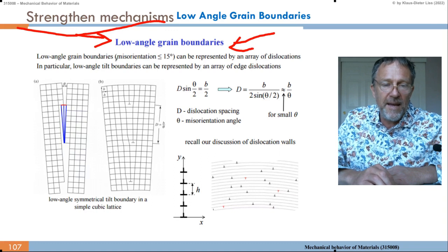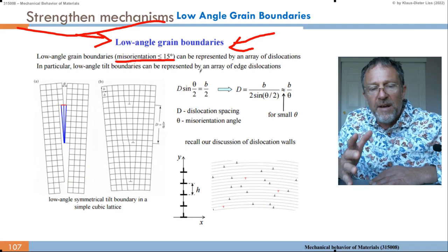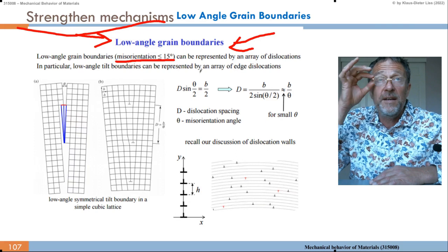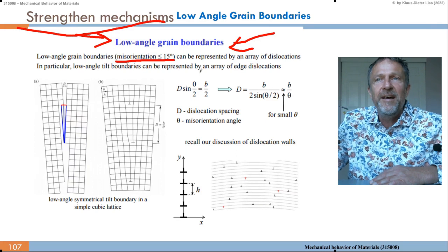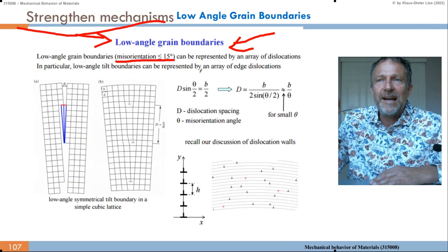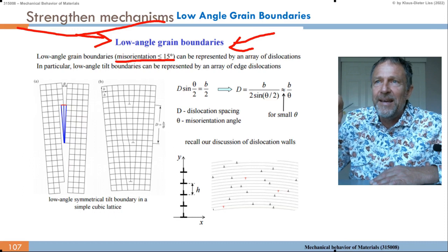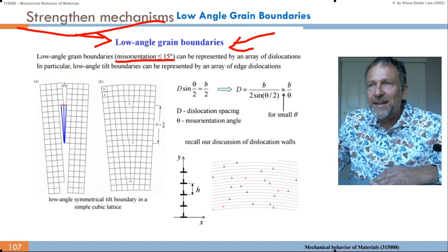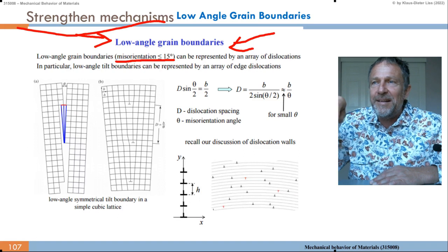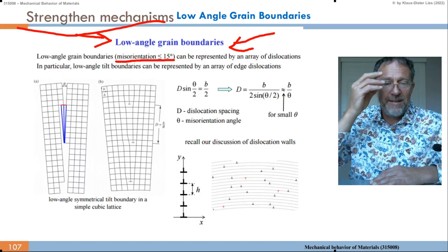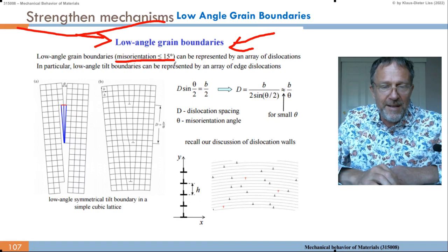And we can say the low angle grain boundaries are defined by angles smaller than or equal to 15 degrees. You know, in the crystal you have many 30 degree angles already, which are given by symmetry considerations. And so then you may go into another lattice plane, or closer to small angles to other lattice planes.